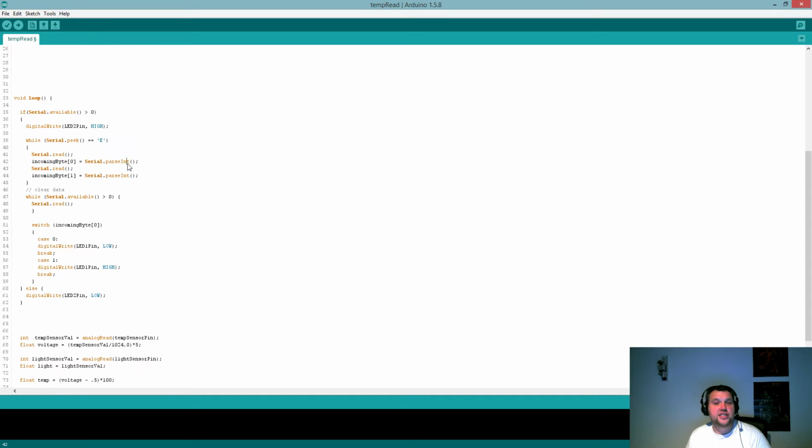We're going to read it as a number because when I want to turn things on and off, I just send it as a value 0 or 1, and I even use 2. Value 2 just means no change to the current state. So if I'm sending a lot of signals and I only want to control a single part, because of this code I have to send the entire string each time. A lot of 2s will be in there, and the 2s just mean ignore this and move on. But right now we're just getting the numbers.